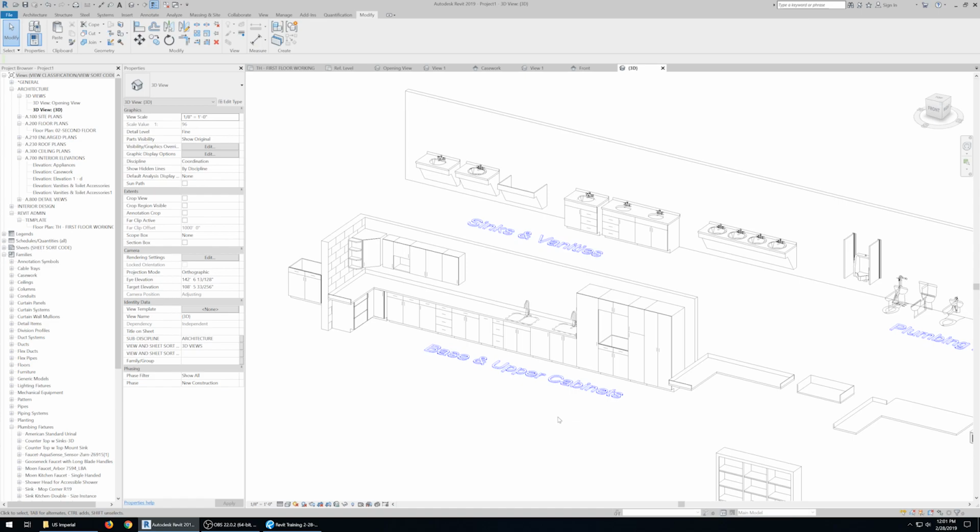It doesn't know, and you have to have what's called a shared parameter. It's a text file that each project has, and when you create a shared parameter, it talks to the text file and says, hey, I got this parameter, it's going to be associated to my doors, and it's going to be a parameter that tells the door schedule, hey, this is a single or a pair of doors.